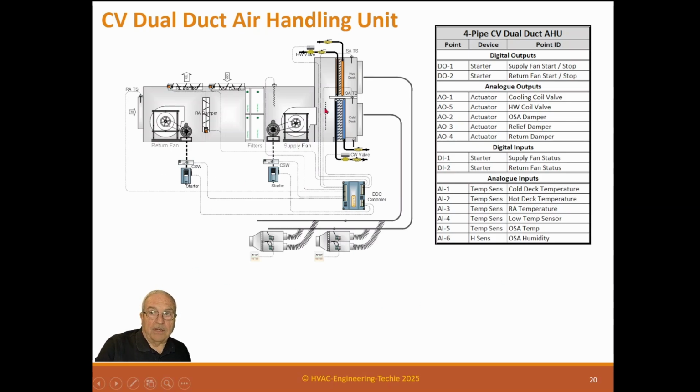We have this air handler, just like the others. It's got a supply fan, return fan. It's got a full economizer. It's got filters. But it has a cold deck section and a hot deck section. And this blast plate, it's just a plate with holes in it, is designed to back pressure this flow to break up any stratification across the cooling coil and to force air up to the hot deck.